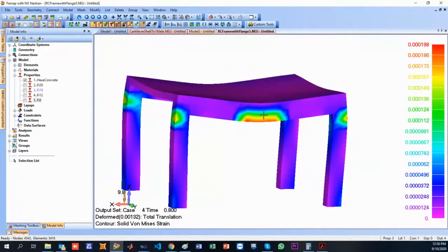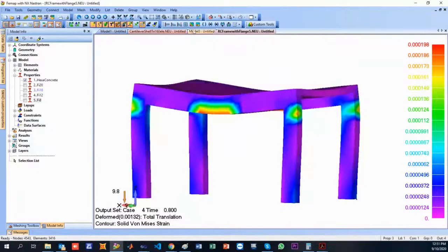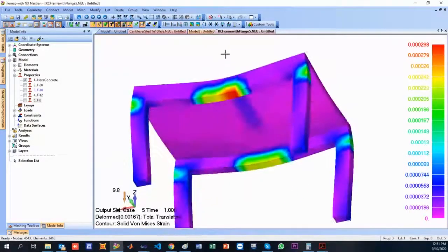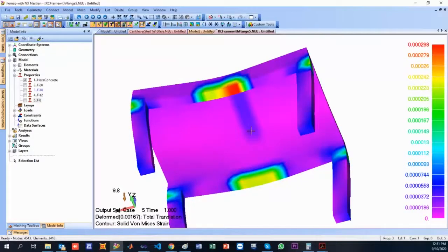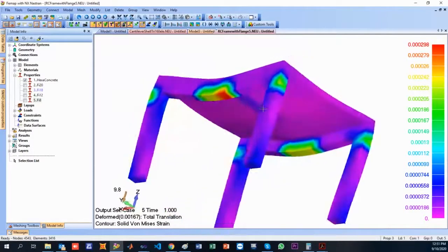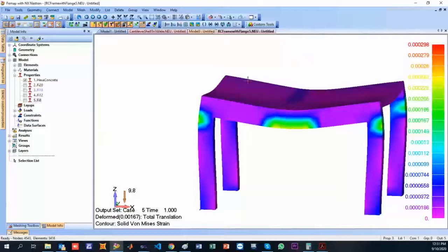One might argue though, look, the bending moment does behave like what they told us. I'll say yes, no objection. But what about if I apply a horizontal load about this point there and the whole thing develops a rotation about the z-axis, so the whole structure will rotate? Would you like to see that happening? We can do it, by the way, if we have time. So let's see then load increment 5. As you can see here, now the slab started to develop also cracks at this area here. But again, the behavior is dominated along this direction.